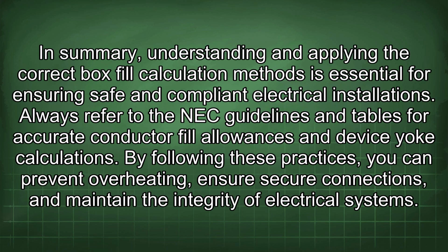In summary, understanding and applying the correct box fill calculation methods is essential for ensuring safe and compliant electrical installations. Always refer to the NEC guidelines and tables for accurate conductor fill allowances and device yoke calculations. By following these practices, you can prevent overheating, ensure secure connections, and maintain the integrity of electrical systems.